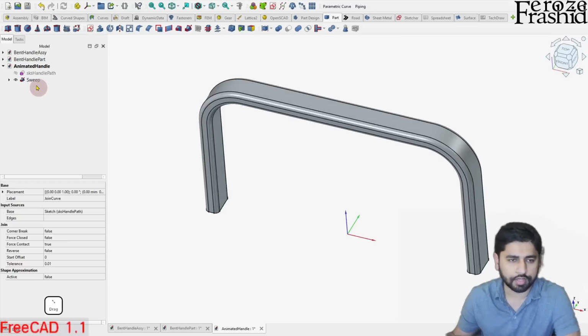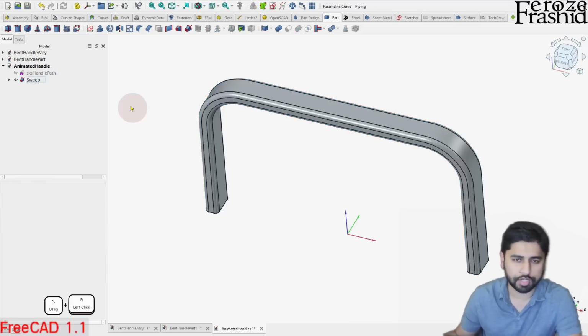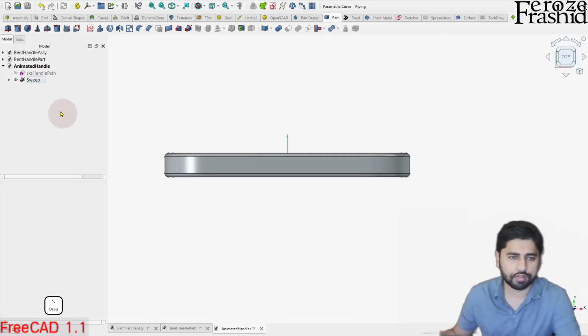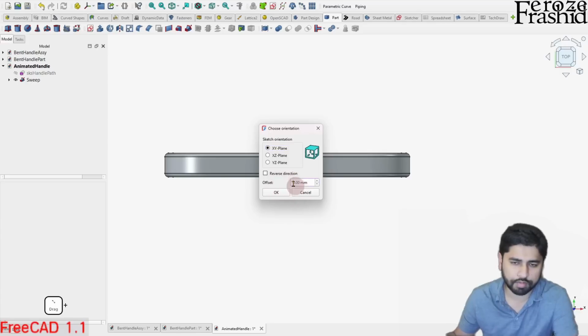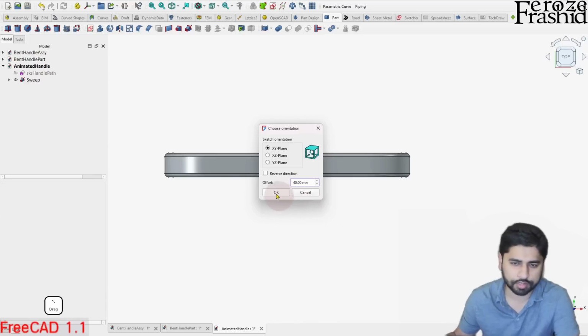All right. Now I want to rename that. Actually, not. Let's not rename it right now. Now I want to have something built in here that will be holding the shaft. Create a sketch on the XY plane, and here we could use the offset tool. So let's offset it by, say, 40 millimeter. Let's see where it takes us, right?